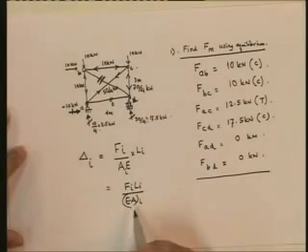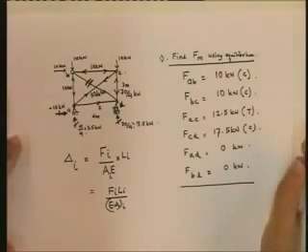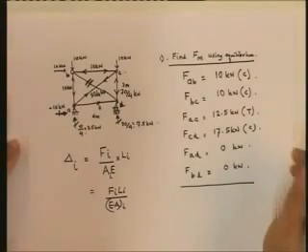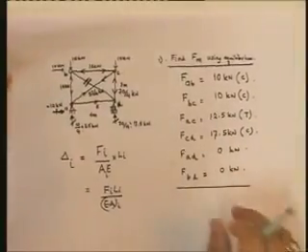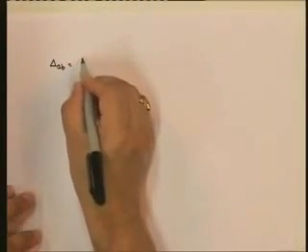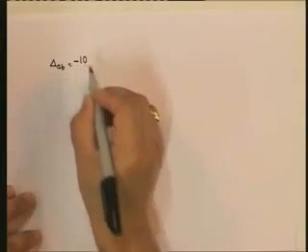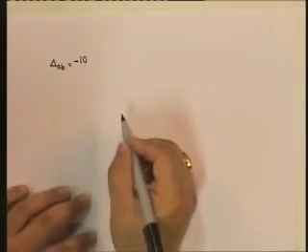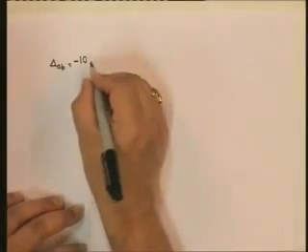Okay, so this way I can find out what the corresponding delta is going to be for each one. Let me write down those values. Given these forces, delta AB is going to be equal to minus 10 — note that I am putting minus because tension is taken to be positive. Since it's compressive, it's going to be 10 multiplied by Li.